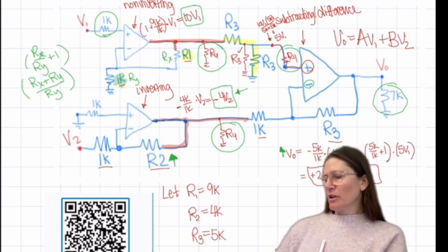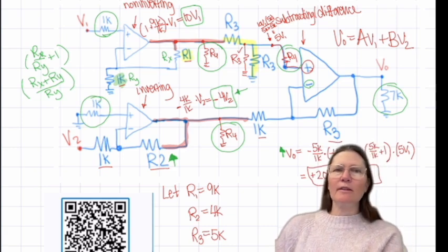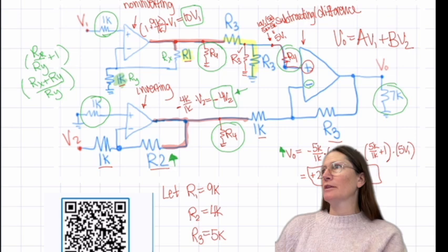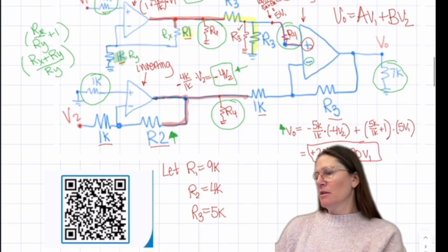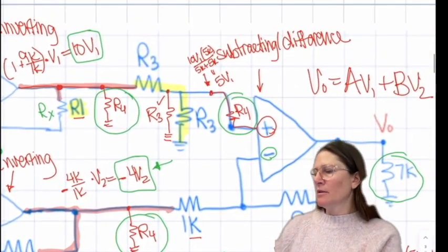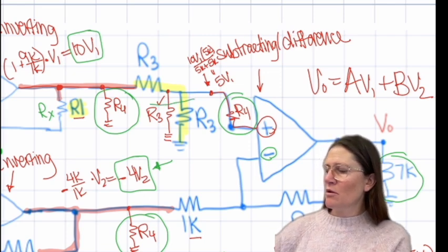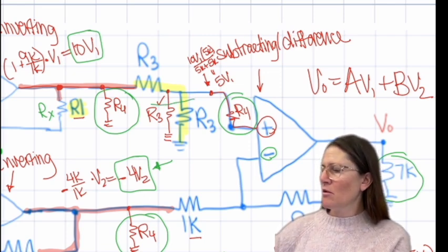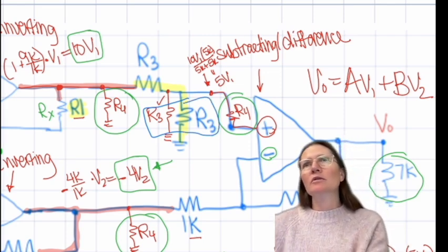And then all the others that are marked are going to affect it, except for this one, K. Again, it's the same as the top one. It wouldn't have an effect. So with the extra resistor that's parallel with R3 that you wrote, to get the two values for that, would you just do two individual voltage divider equations and then combine them, or would it be just the same because they're parallel? So I would put them in parallel and then use that in the voltage divider equation.